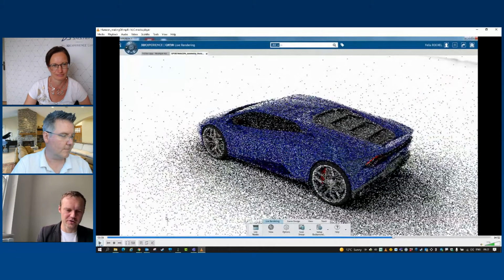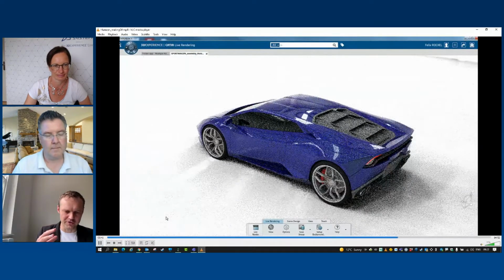And then, for example, in Imagine and Shape, it's easy because you can keep that surface together easily, and then at some stage you can trim it in GSD. You can switch to GSD and just trim it and fillet the trim edges, and then it looks like a completely finished model. But in interior, for example, there are hundreds of different parts. So what you usually do in that case is use the 3D sketch that keeps parts and splits in place, and then you just choose which ones you want to keep in one surface or which ones you want to separate.